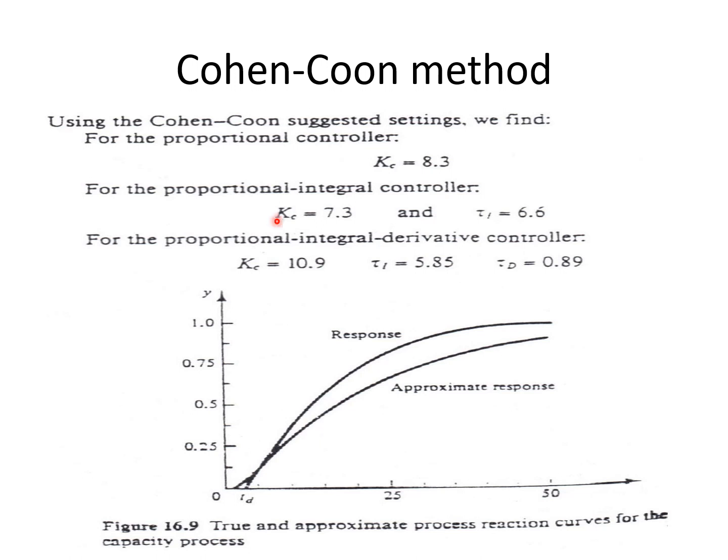So this is from that equation, the approximate response that you got, and the final response you get. So it's a little bit off, but roughly this is just enough to get your controller settings, which is the most important thing. So using the Cohen-Coon method, you can decide, if you have a proportional controller, this is going to be your Kc.